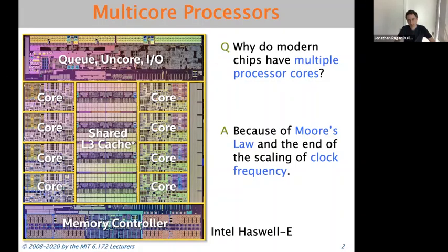At the same time, and this is something that's not talked about that much, it happened that the processor cores we were building at about that point were starting to hit diminishing returns in terms of their ability to invest extra transistors in exploiting instruction level parallelism. So investing extra transistors in building one core that could run multiple instructions at the same time at larger and larger scales. So how could we use twice as much logic to do twice as much work, on only one stream of instructions or one thread?